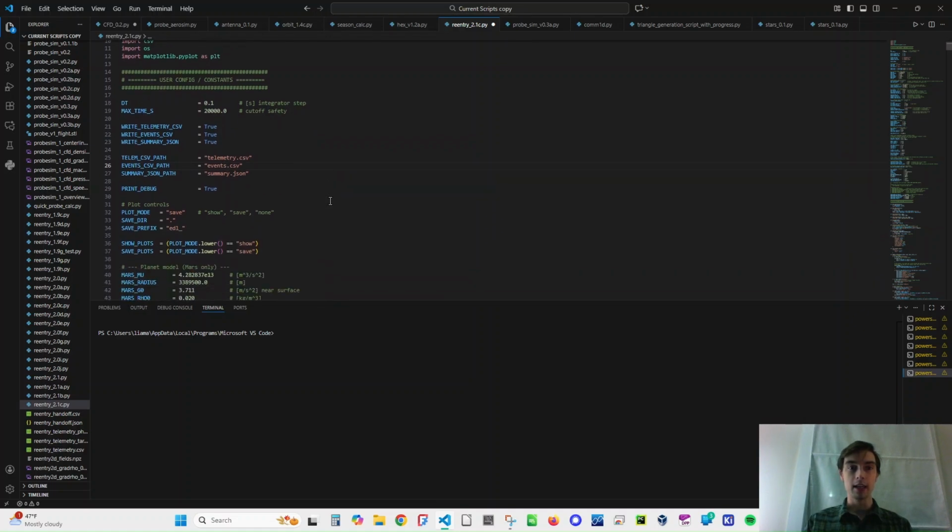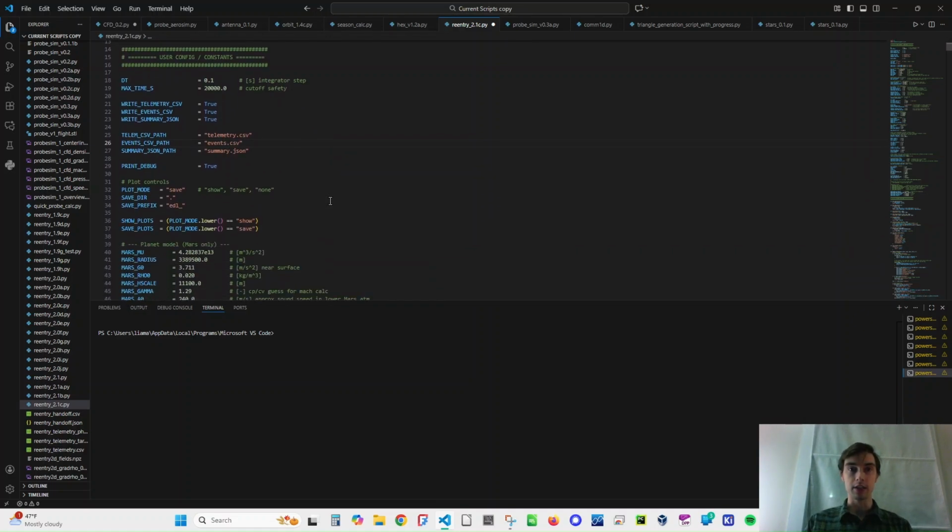So basically, this section is to categorize and simulate the EDL portion, or the entry, descent, and landing section of this mission. Of course, we'll have our probe plus aeroshell, and this will detach from our orbiter, and this entire section has to perform a retrograde burn, and that is to lower periapsis.